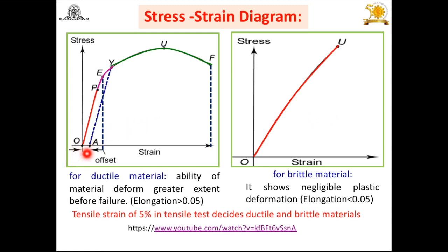Again here you will find I have drawn one line through this E with a dashed line. The area under the curve OEA is known as resilience, which is associated with the stiffness or elasticity also. The energy absorbed, or area under the curve, you can say the resilience, is the energy absorbed during this deformation in the elastic region. Try to understand. And then F here, look at this, another line which is drawn with F. The area under this whole curve here is known as the toughness.